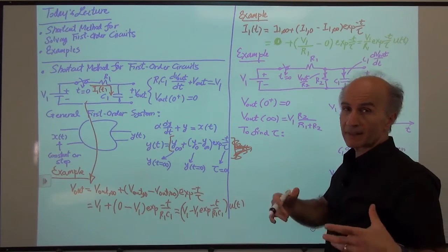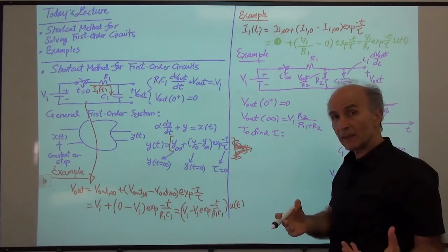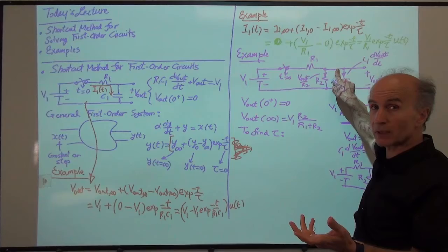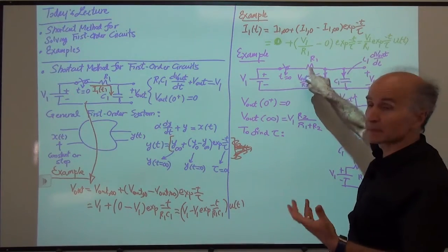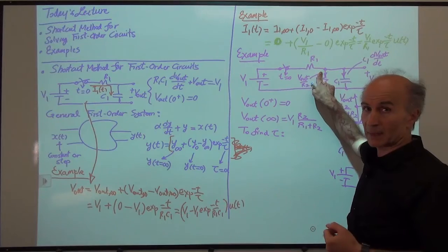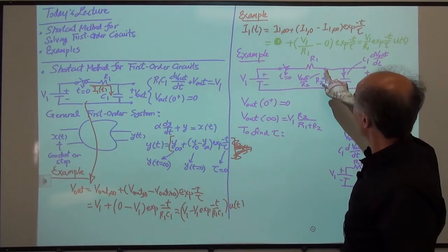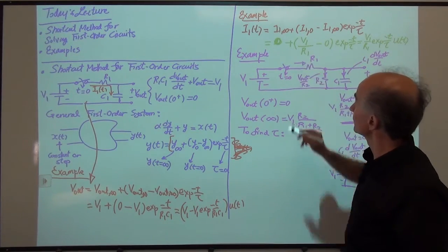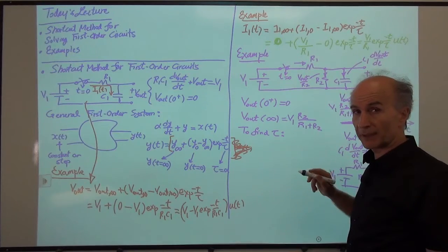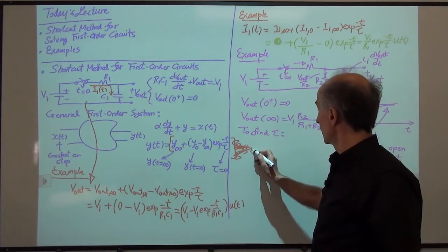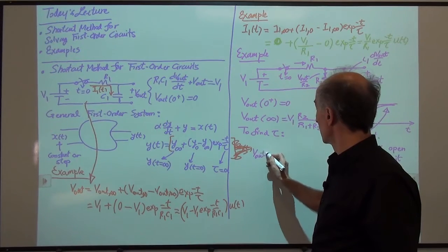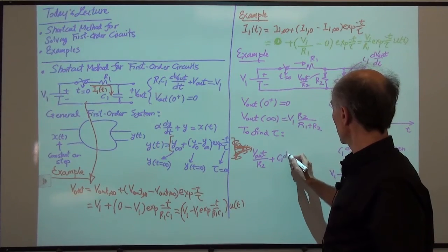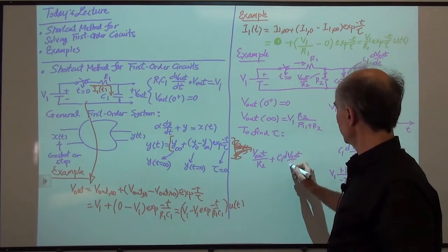All right, so in a sense, I'm writing a node analysis here, right? Because I am assuming there's a voltage here, V out, that is not known. And I'm finding all the currents and then writing a KCL here. That's what's happening. Okay, so this current is this much, this current is this much. How much is the current going this way? That would be the sum of these two currents, right? So that current would be V out over R2 plus C1 dV out over dt.